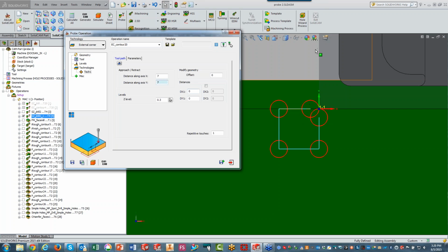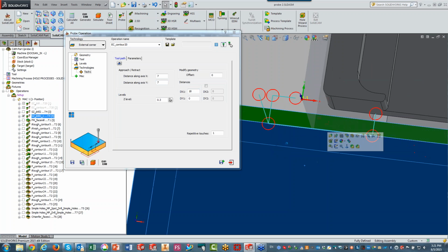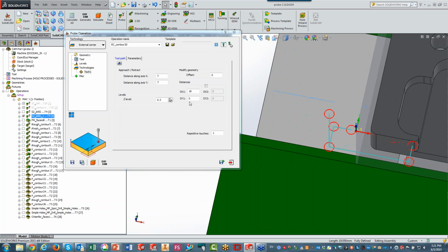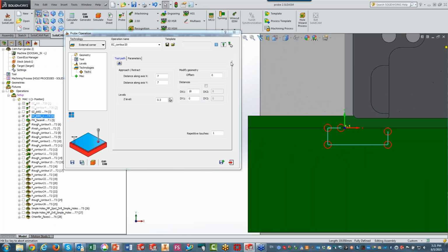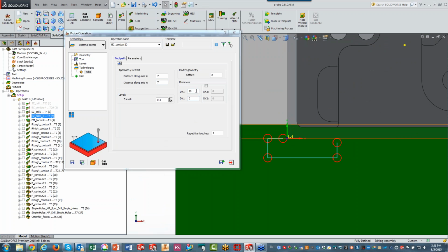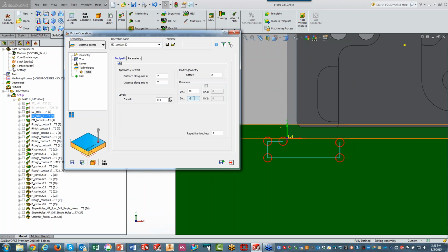Now, as far as where along here do I want to check, that's what we have over here. Note, I can say, okay, let's move it out that much in my X direction. Okay, you can see that over there. And that's exactly where it's going to hit on the stock. Now my Y direction, let's take another look at the very top view and zoom in over here again. You can see we have the X and we have also the Y. I want to have the Y a little further out towards the middle of the part. And that's it. Wait, one more thing.